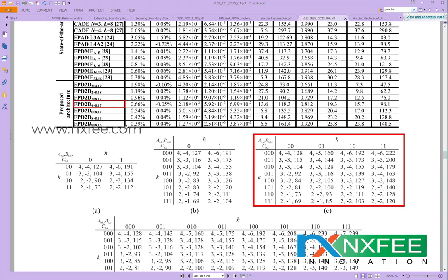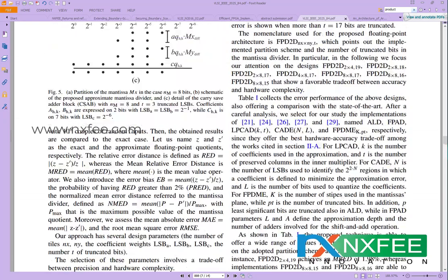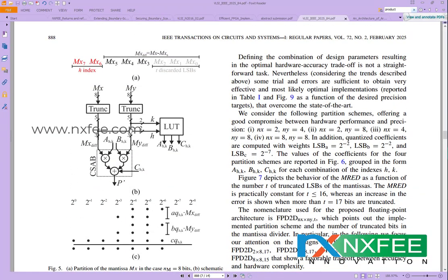For the proposed designs, we choose XOR mux based addition operations and XOR mux based subtraction operations. This reduces the number of logic gates in the addition and subtraction operations of this division part. The conventional designs occupy 5 logic gates in the addition and subtraction operation, but the proposed design takes only 2 logic gates and 1 multiplexer. For that reason, it comes with a simple, compact proposed architecture.